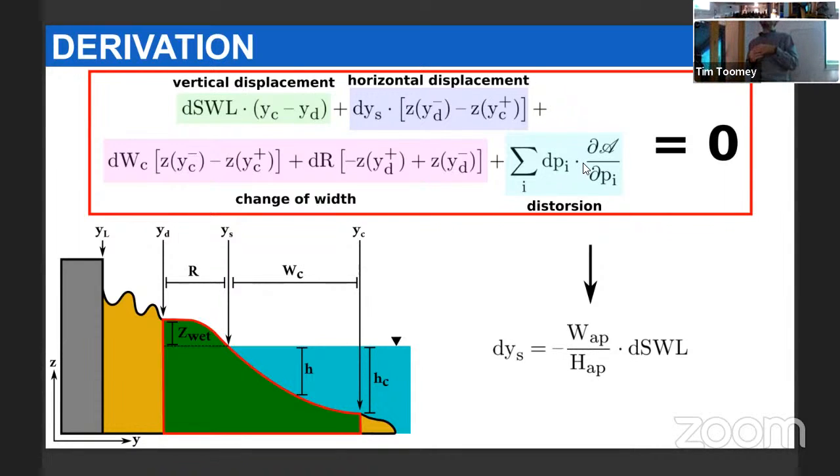So there's a lot of dependence on the sediment nature, not only its size, but also material shape. Yes, absolutely. Mobility there depends, like the mobility everywhere. The critical mobility that you were defining there depends on the dimension of the grain.